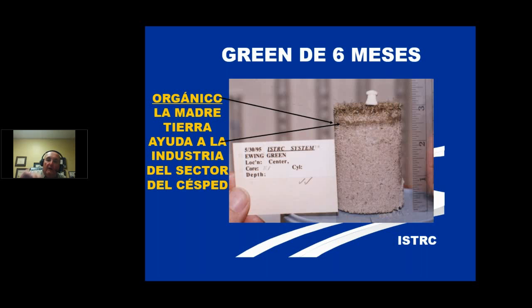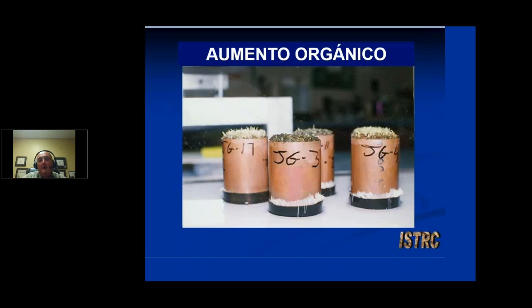So we're looking at how easily soil gases can be released and oxygen rediffused in the soil. Here is a classic example of the basic properties of high organic content, where organic matter swells with hydration. With the swelling, it fills the pore space and starts slowing down my water penetration and my ability of oxygen to penetrate the soil.